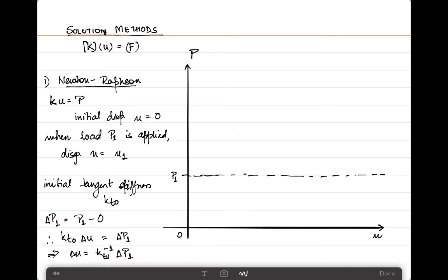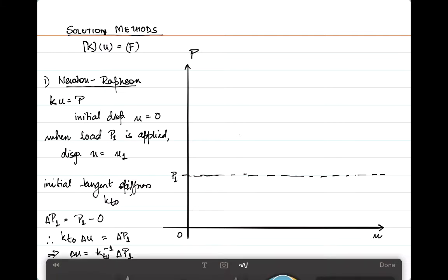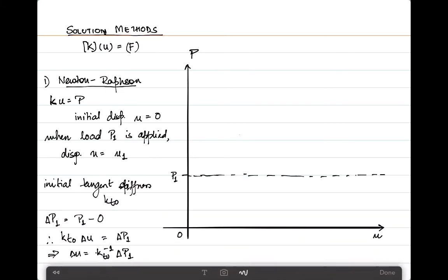Now, what I would like to do is show you graphically what happens. If I have a certain load P1 which is applied initially, I can find the tangent stiffness based on the relation that I just described to you. If I draw the tangent stiffness here, it's just a linear tangent stiffness up to point P1, up to load level P1. I hit a point here which I call point A, and I know that this is just an initial tangent stiffness. It's not the actual tangent stiffness which should be for that certain point in time for this system, or the linear spring in our case.